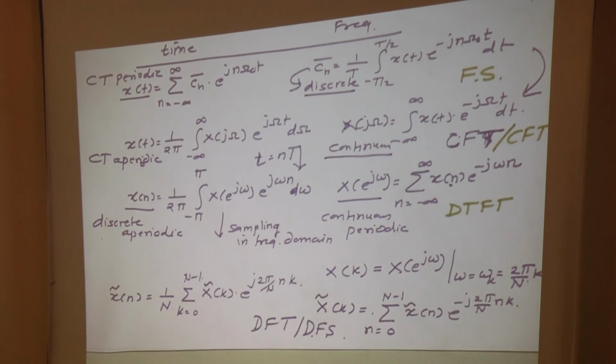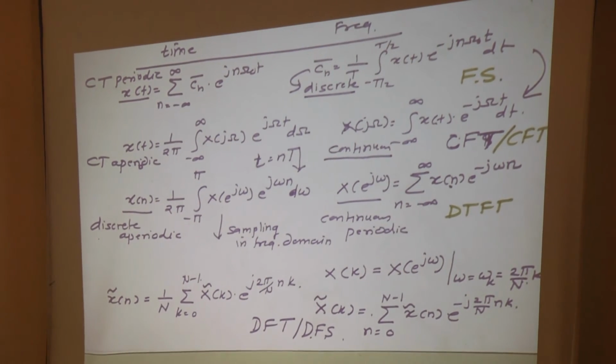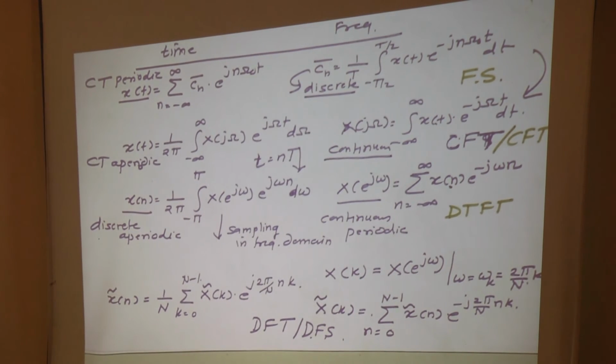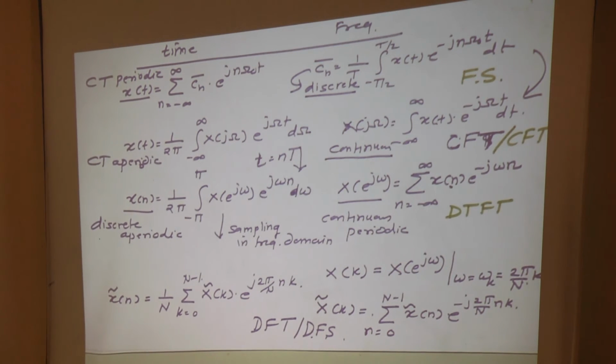If the length of the signal is finite, then that is also not required to be checked, because a finite length sequence of finite values is always going to be absolutely summable. So for these two equations you require to check only the third Dirichlet condition, which is absolute summability.